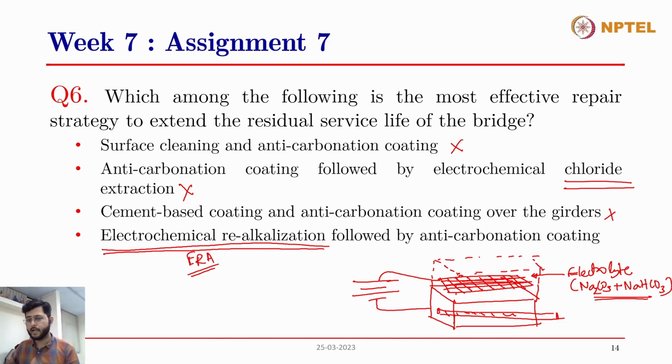This alkali solution gets inside the concrete, and at the rebar location, which is the cathode location, hydroxyl ions are getting accumulated. That will restore the passivating film, and this will realkalize the concrete. The alkali solution will realkalize the concrete, and within a few months or days or years, depending on the concentration and the voltage applied, within a certain duration, we'll see that the concrete starts to realkalize. It starts to gain the pH. So this is the ERA technique.